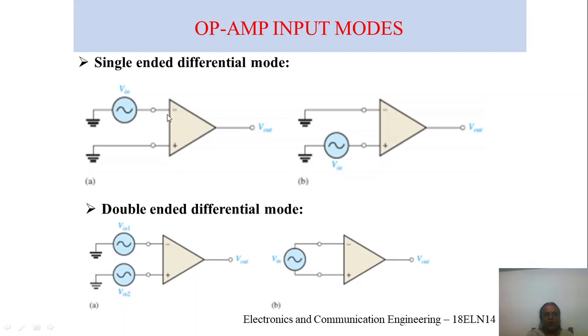In phase or out of phase. It means that if the input and output signals are 180-degree out of phase, then it is given to the inverting minus. If the input and output signal voltages are 0-degree and in phase, then the input signal is given to the non-inverting. This clearly indicates how we are going to get the input and output waveform. I will be showing you in the inverting and non-inverting amplifier when we explain in the further sessions.